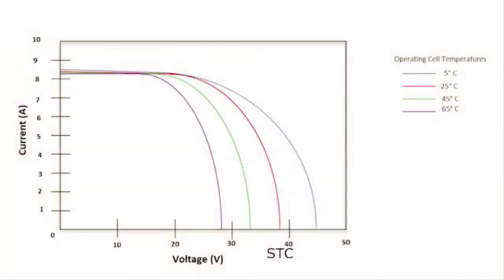There's also a temperature dependency value because solar panel voltage decreases as the cell gets warmer. So the efficiency goes down slightly from standard test conditions. Now, this isn't a big deal for efficiency, but it can be really important as we begin to choose proper wiring. We'll discuss that in the next course. Other information that's usually included in the specification sheets are the module size, weight, the impact loading, the fusing, and a few other electrical guidelines.